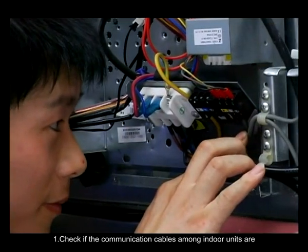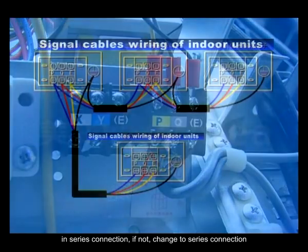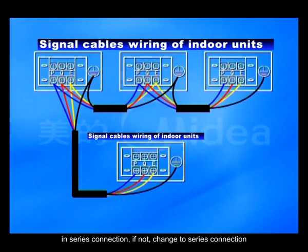1. Check if the communication cables among indoor units are in series connection. If not, change to series connection.